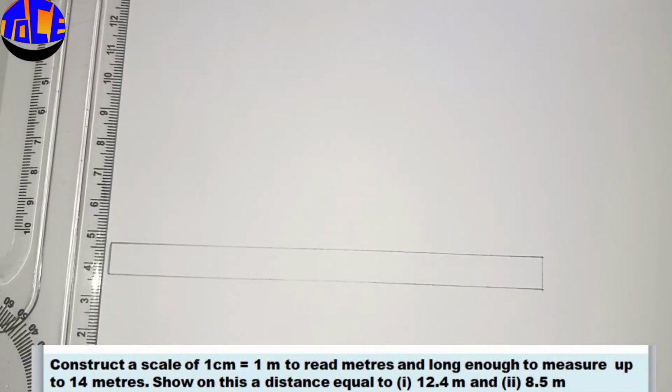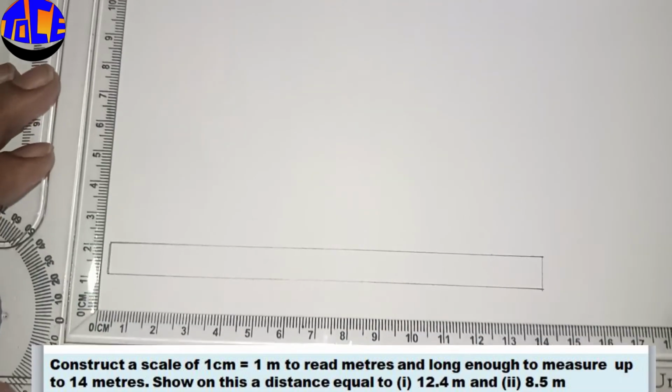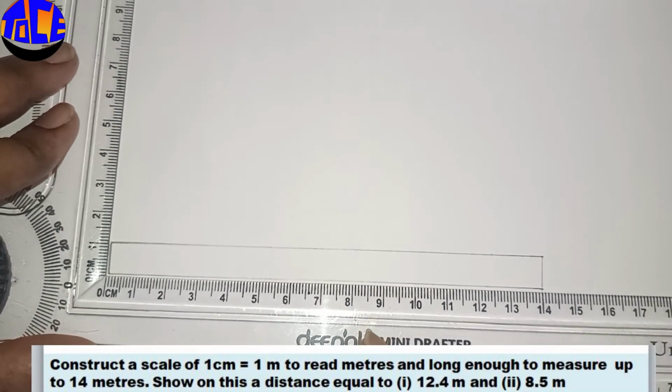So this is having a length of 14 centimeters and width 1 centimeter. Now we need to divide this 14 centimeter length into 14 parts because we need to measure up to 14 meters. So one part will be 1 meter. In such a way we'll be having 14 parts so that we will have 14 meters. So we are dividing this into 14 parts. 1 centimeter will be one part.